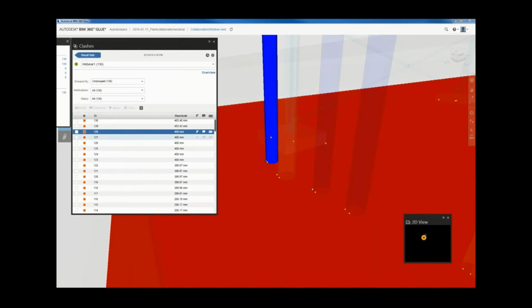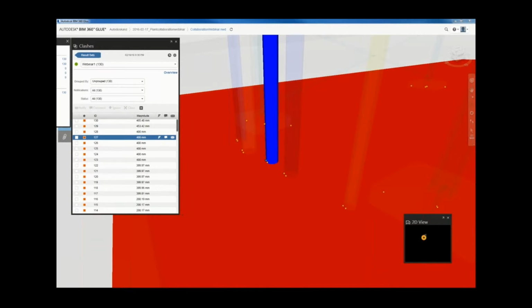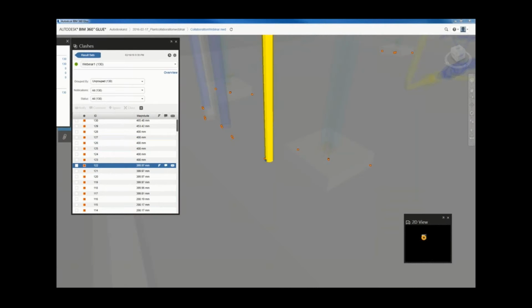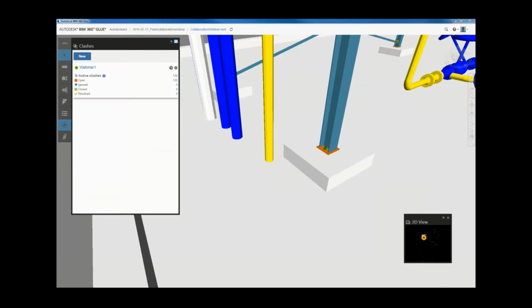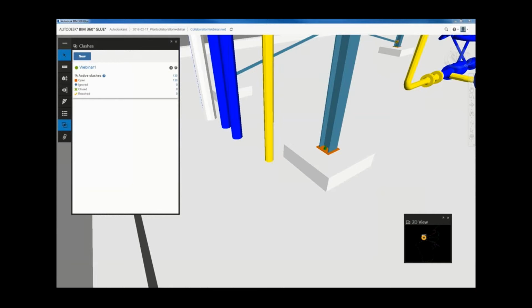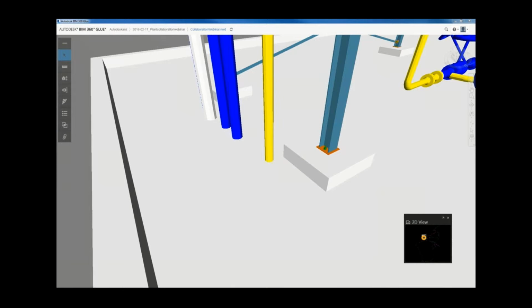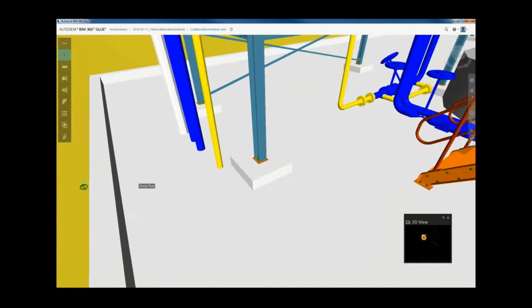If anyone remembers from the Navisworks portion, some of those advanced steel models were clashing with the pipe, so we are going to see a lot of those coming through there too. Again, it's very handy that we can do all of these clashes in the cloud, and they are part of that cloud model. It doesn't matter what happens if we disconnect, all of that is stored in the cloud, and we don't have to worry about who did what, because we can track all the activities.